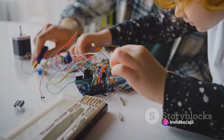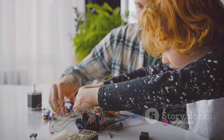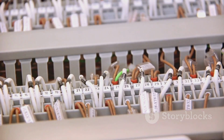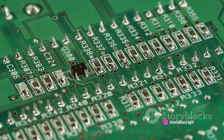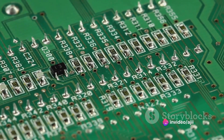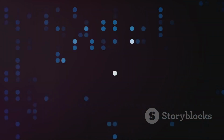However, if the voltage is applied in the direction from the N-type to the P-type material, the depletion zone shrinks and current starts flowing. This is known as forward bias. To put it in simpler terms, in the forward bias condition, the diode acts like a closed switch, allowing current to flow. But in the reverse bias condition, it behaves like an open switch, blocking the current. This unique property of allowing current to flow in one direction and blocking it in the other has a wide range of applications, from rectifying AC to DC, to protecting circuits against reverse polarity, to controlling electronic signals and much more. Now that we've got the theory down, it's time to see this in action.